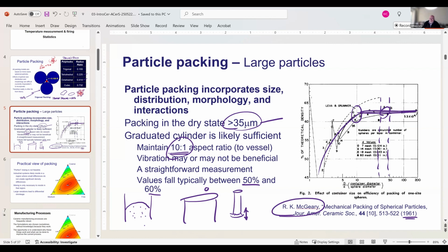That says if I want to blend large and small particles, my large particle should be 10x my small particle. If I do 7x, I don't get the best packing. And partly it's because the size of that particle in between the other particles is looking at a little volume within that large particle network, and it needs to be at least 10 times larger than the particle.